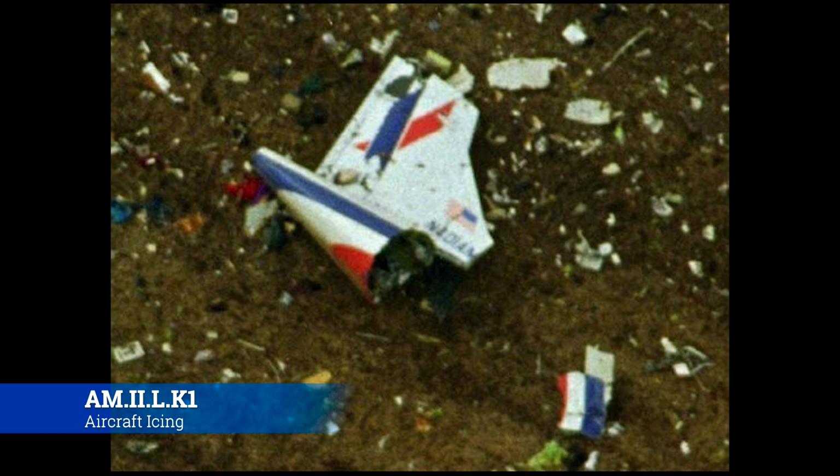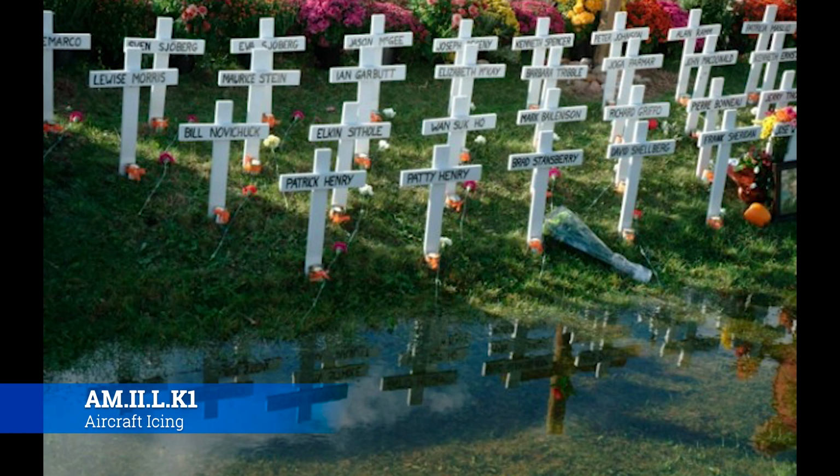As the airspeed comes up, it sends an overspeed alarm. So they retract the flaps, and as they retract the flaps, it took away the last little bit of surface area that they needed to maintain the lift they had accumulated. As that happens, the plane entered into a roll, and they were never able to recover. Now, this just goes to show how serious ice can be to an airplane.